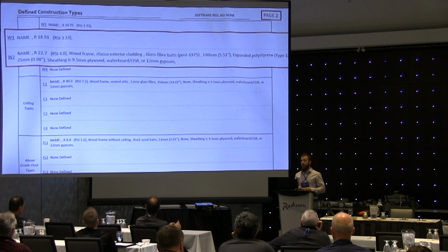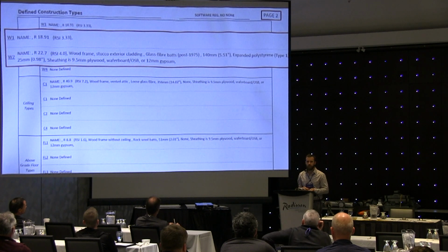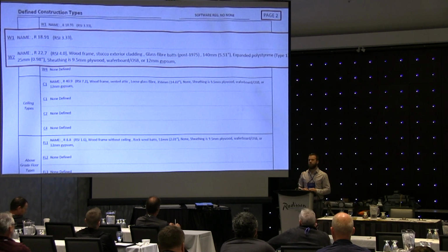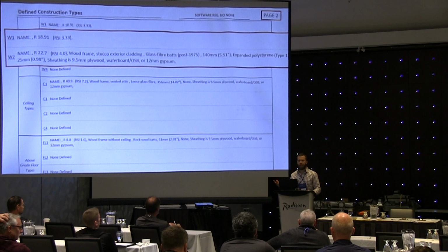To your question about what we're talking about when we're talking about insulation in the walls, I want to ask the audience, what is the difference between nominal thermal resistance and effective thermal resistance? Effective takes into account all of the components used for that assembly. Okay. So if you were to ask someone on site, what's the insulation of those walls? And they're like, the walls are R20. What are they probably talking about?